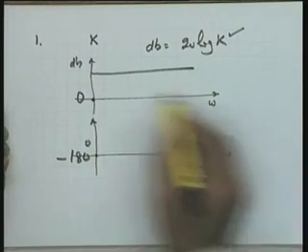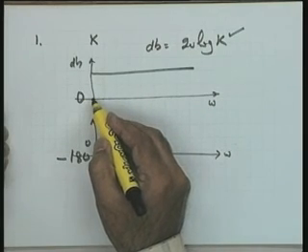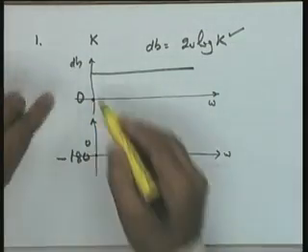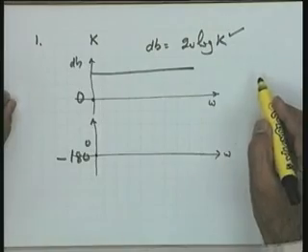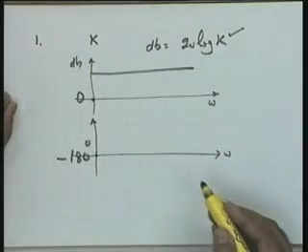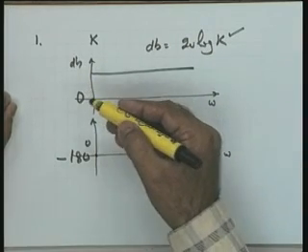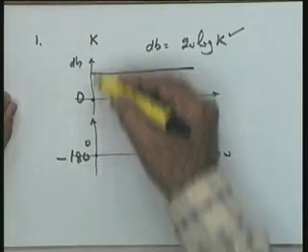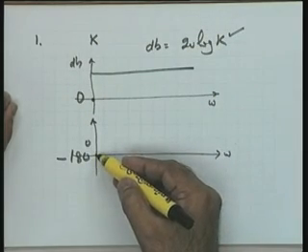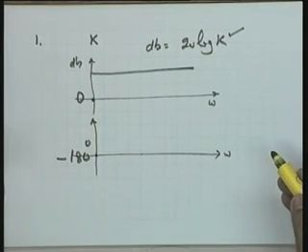How about this axis, please, as far as the origin is concerned? Will it be 0 radians per second? As far as this axis is concerned, I am telling you about the axis. I will repeat my point, maybe I have made some wrong statement. This is the Bode magnitude plot, the frequency on the log scale and magnitude on the linear scale. And I am telling you, for the problems we will be confronted with, 0 dB as the starting point on the vertical scale is nice. Similarly, minus 180 degrees starting point on the vertical scale will be most appropriate with respect to stability analysis.